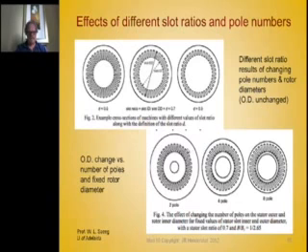I'll say it the other way: as you increase the number of poles, the cross section of copper is the same into the paper, but since the length is longer, you require more end turn extension out the ends. It goes down with 4-pole, and with an 8-pole, it only spans 45 degrees. The coils are real short, you see.